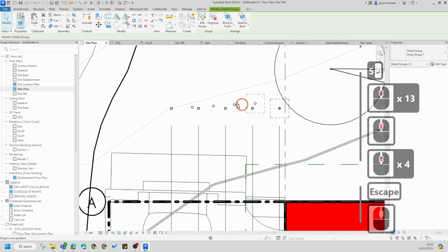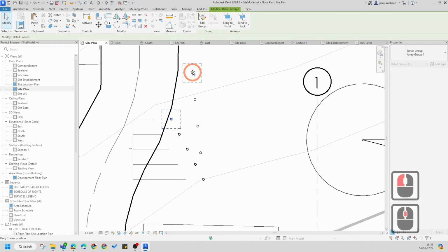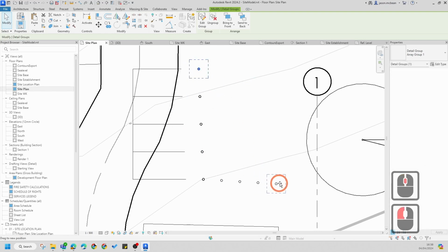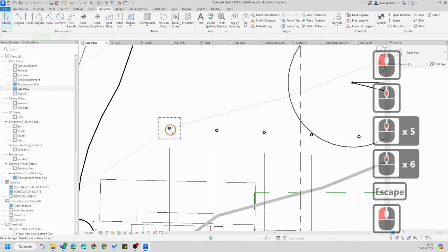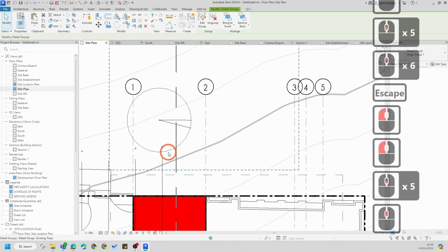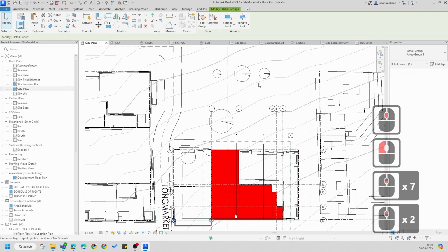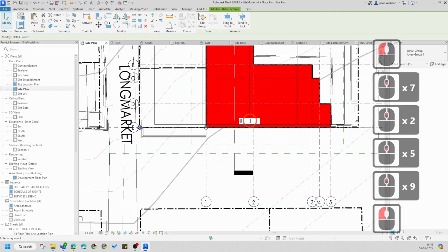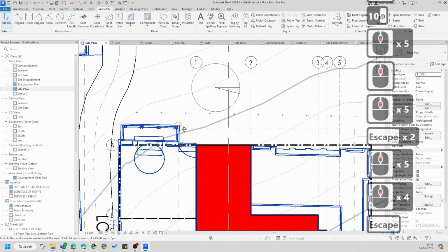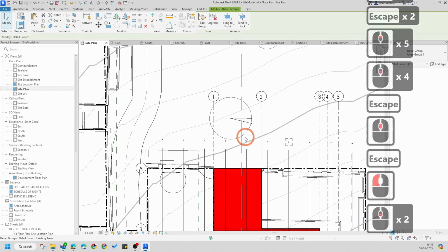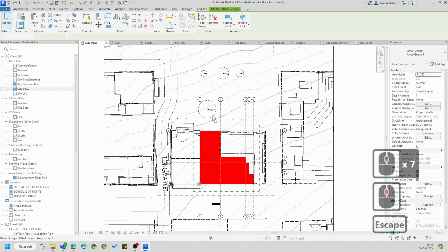Now what's great is if I move these bollards, you'll notice that it'll try and keep that repetition going wherever you go. So if you do a series of bollards, this is very quick to do. Okay, so I can move this bollard over here, and I can move this last one to the end. And remember, we're trying to stop cars, so you can go and specify how many of these you need here. 10 maybe, 10 bollards, and you can see I can drop in 10 bollards. That's quite a neat function. Just remember the array function is hard to work with sometimes.